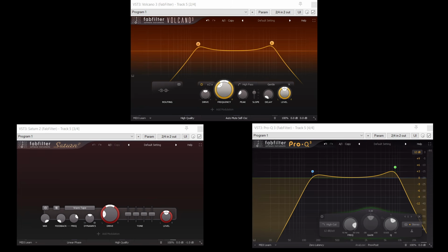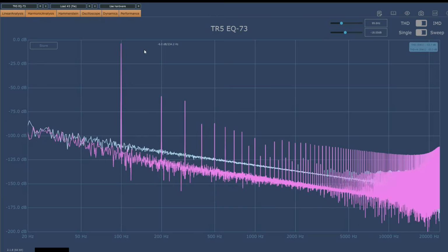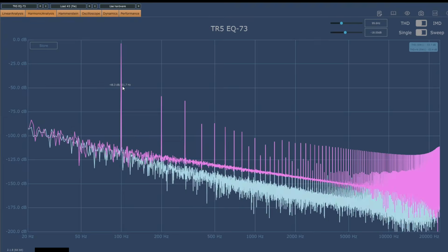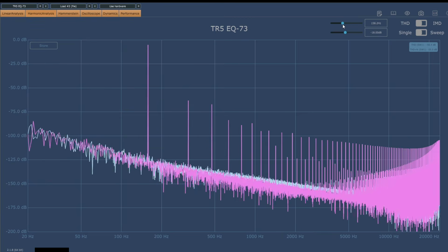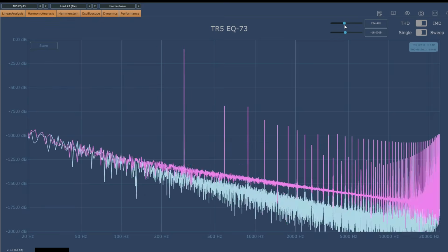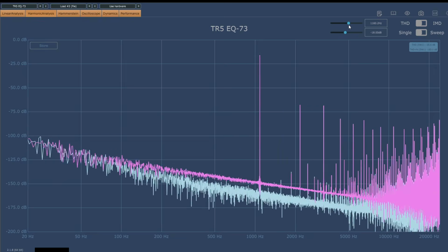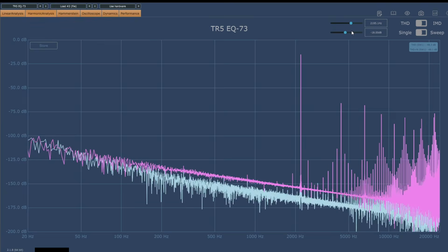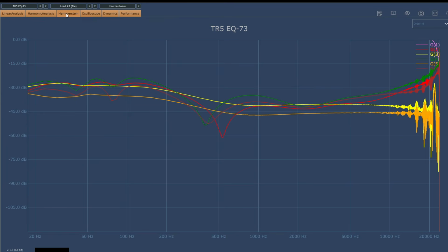But you may be wondering at this stage, what about all the other frequencies? We can see what happens to a 100 Hz test tone, but we can't assume that other frequencies will be affected the same way. Do we have to laboriously set our test tone to incrementally higher frequencies to get a proper picture of how a distortion will behave with a full range signal? Well, yes and no. That is what needs to be done, but that's essentially what the Hammerstein test does, which removes the laborious part and also provides a better way to view all the results.